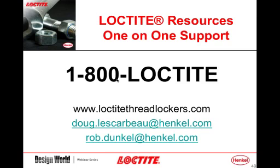Actually, there's some variability to that question. If you have a small bolt, typically 3/8 and under, we say typically 1 drop is more than adequate. With larger bolts up to maybe 5/8, you might put up to 3 or 4 drops. 1 inch, you might have to put like 6 or 8 drops. What you really want to do is just put a drop on, considering if it's a smaller size. When you put the nut on and run it around, you'll typically find that it spreads itself out.